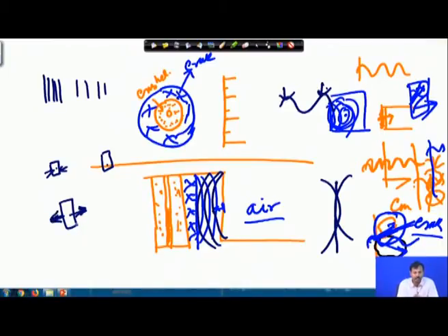So, basically the particle is under a tensile stress at this position. What will happen? The tensile strength of the rock is the minimum one, almost 1/7, 1/8, 1/10, 1/12 of the compressive strength. As this portion of rock is subjected to tensile stress, long cracks generate here because of tensile failure.